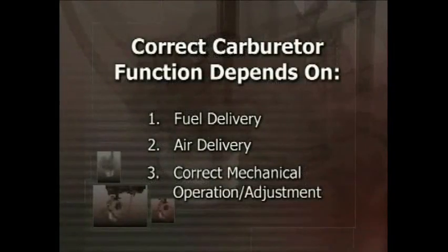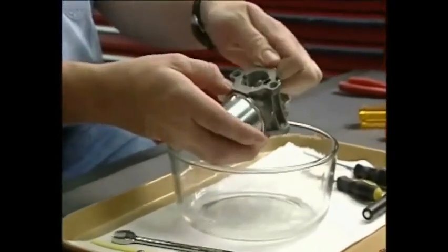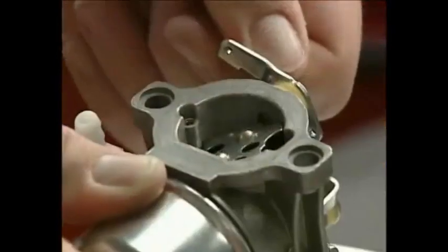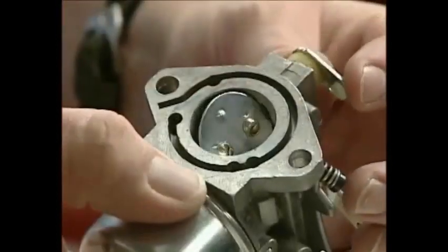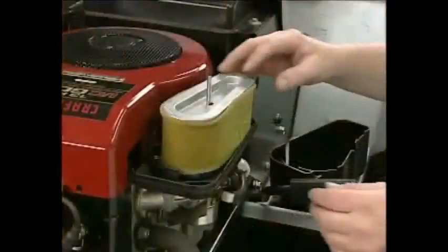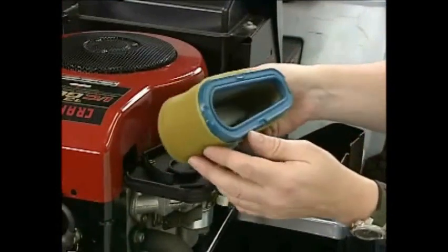A carburetor is a mechanical device that combines fuel and air. The fuel and air are usually metered and mixed. It stands to reason then that problems will typically be with the mechanical nature of the device and/or with the delivery of fuel and air in the proper proportions. Carburetors use fresh fuel, clean air, and up to 4 moving mechanical parts. The mechanical parts are choke shaft, if equipped, throttle shaft, float, and inlet needle and seat. If any of these are unable to perform their function, the carburetor will fail to perform properly.